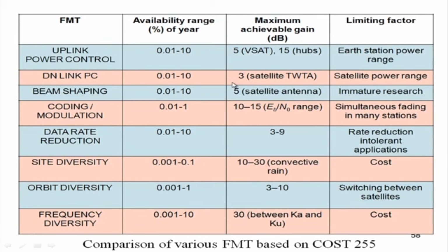So even with a 3 dB increase in EIRP, you do not enter the nonlinear region. 99.99% of the time you are operating normally, and only 0.01% of the time you will be introducing this fade mitigation. So the rest of the time you will be operating at 3 dB less power, and to compensate for the downlink fade you use the additional 3 dB power only during this time. Not very advantageous, but this is possible.